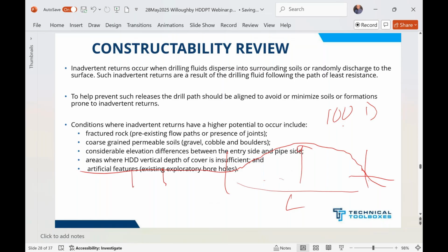So what the contractor will do in his pick plan, he'll have rollers out here, and he'll have them at least every 50 feet. Most contractors, if you tell them 50, would have those rollers about 40 feet apart, because out in the field things get moved around, get kicked. He doesn't want to overstress the pipe, but he would have those rollers about whatever you told him that distance was. Now up here, he's going to have a support every 40 feet, but it's going to be a backhoe or a crane, whatever he's using to pick that pipe up and support it, but it'll be every 40 feet as well, okay?